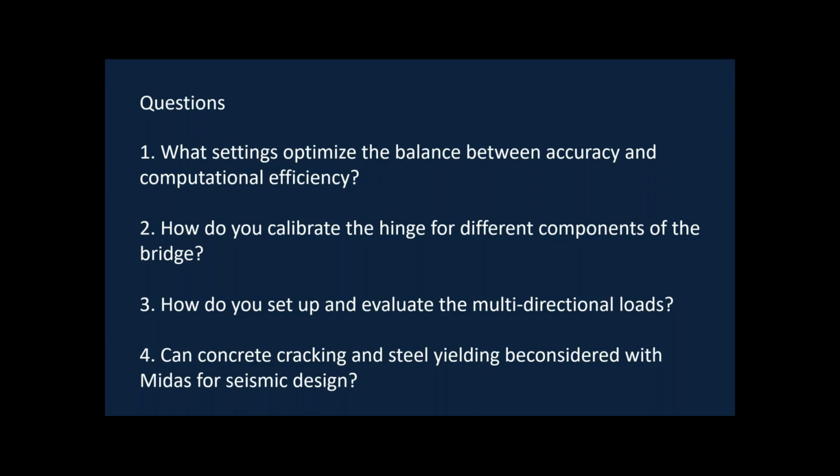Coming to the third question, how do you set up and evaluate the multi-directional loads? For this, we know that when we evaluate the response spectrum analysis, or even the pushover analysis, what we want is 100% in one direction and 30% in the other direction, that is, the multi-directional loads are to be applied. So to cater for this, when we are considering the pushover load case, let me just share my screen again for a moment.